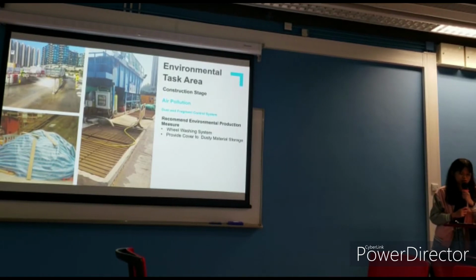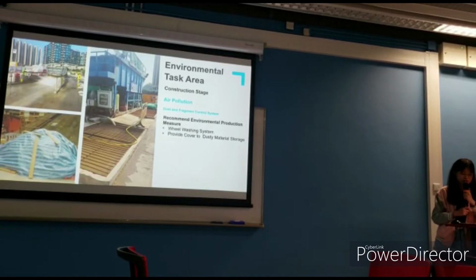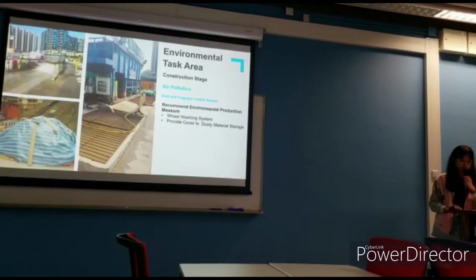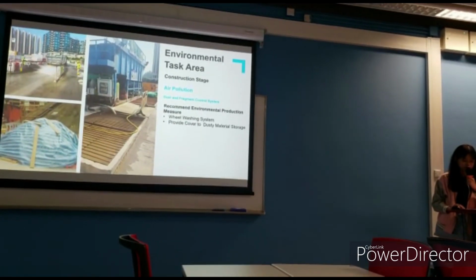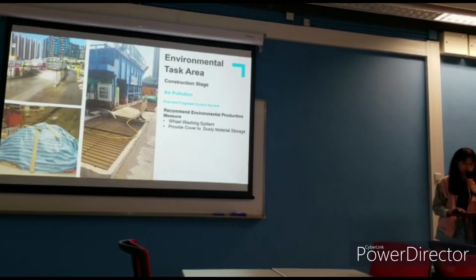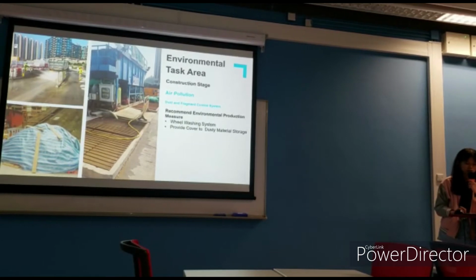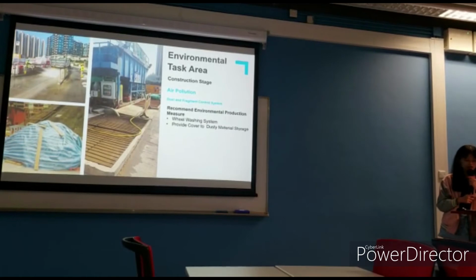And during the soil transportation, the delivery trucks may bring dust and fragments to the public road, which may cause complaints from the public and a fine from the Environmental Protection Department. So the main pollutant for the air pollution will be dust. So dust control mitigation measures should be carried out in our project.